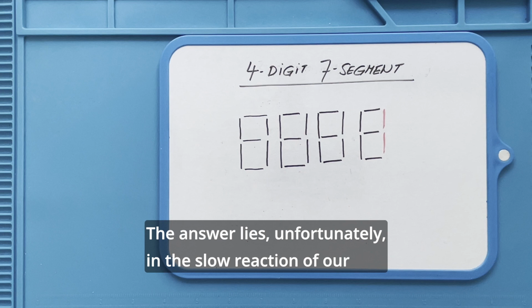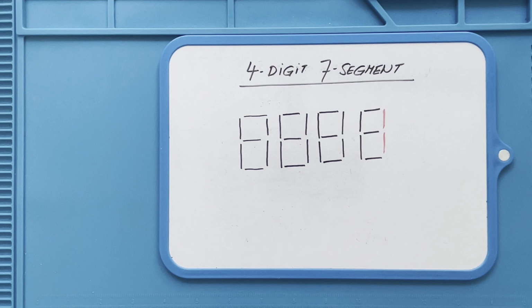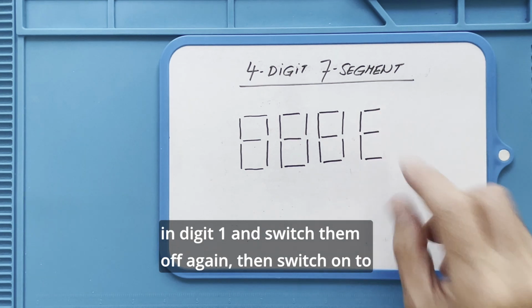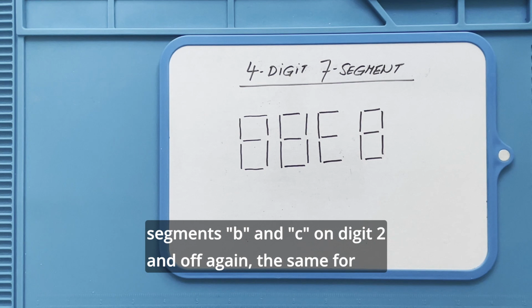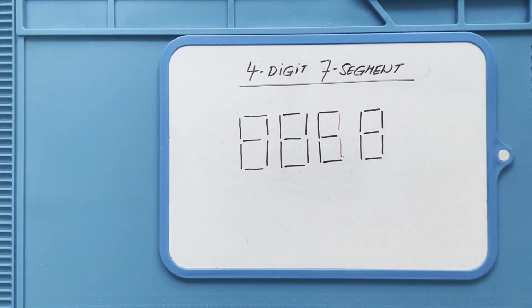The answer lies, unfortunately, in the slow reaction of our brain and our eyes. The microcontroller will first light up segments B and C in digit 1 and switch them off again. Then switch on the segments B and C on digit 2 and off again. The same for digits 3 and 4.